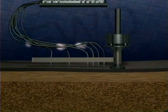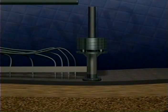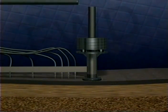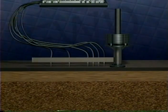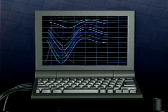Naturally, the pavement deflects most at the center of the load and less farther away. We call the depression caused by the load a deflection basin. Each sensor produces an electrical signal in proportion to the deflection it measures, and the signals from all of the sensors go to the computer where the data is stored.